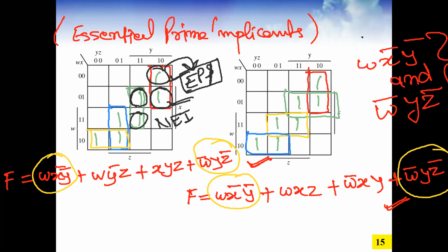Check the first minterm. Can you combine other than the blue, the first minterm of this group? Yes. Rather than vertical in blue, we can also combine this minterm horizontally with the neighbor. Okay, check the next one also. Yes, I can. So it means both can be combined in a different way, so it's going to be non-essential. Clear? Non-essential, because there are possibilities that both minterms can be combined.